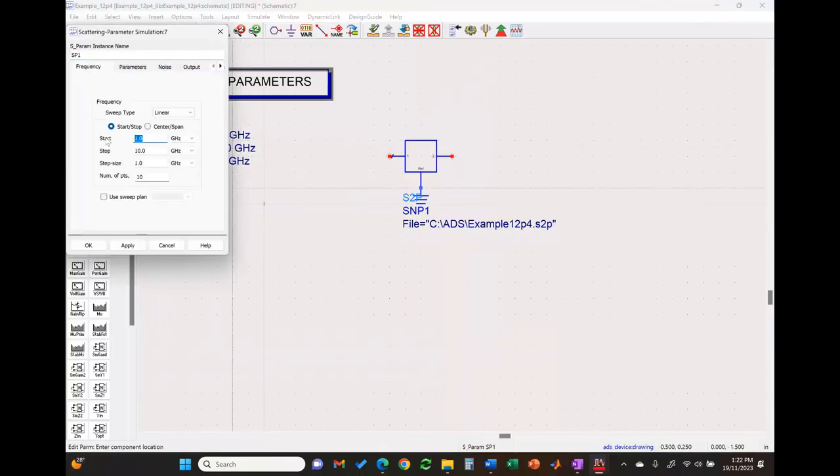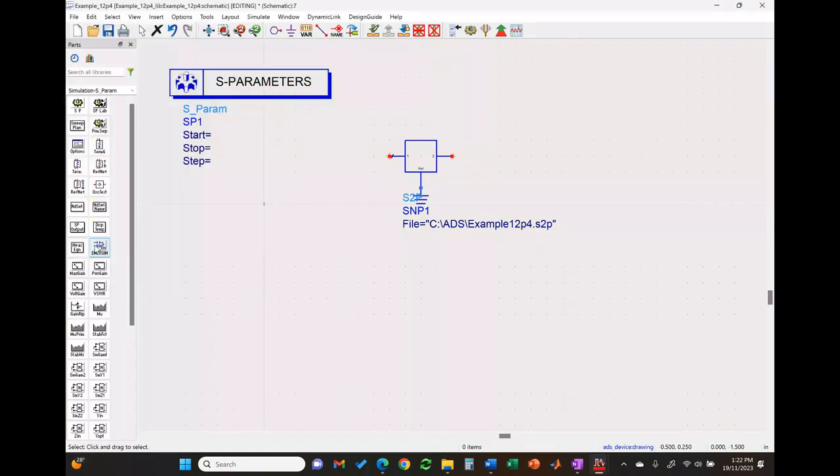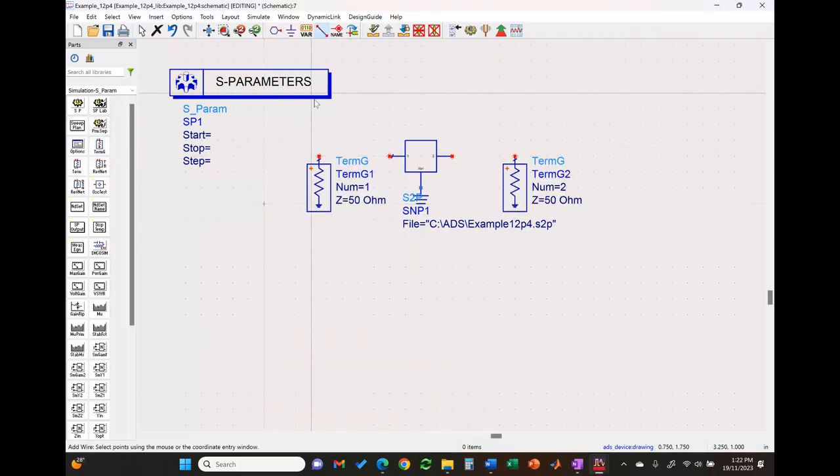It is passivity. No, I think this is related to being lossy or not. Press OK. Then you put your simulation as S-parameters. This is again from 3 to 5 gigahertz. And I can select 101 points. Or yeah, we do the analysis first at a single point for stability.